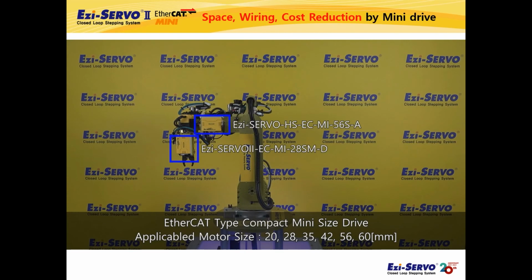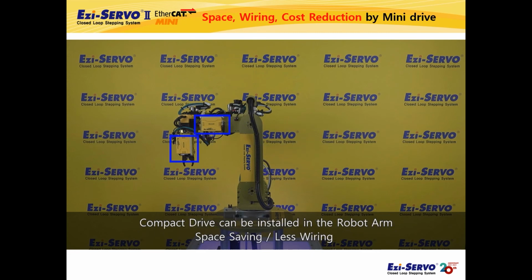First, because the mini drive is small and lightweight, it can be installed directly on the robot body. Of the 7-axis, Ezi-SERVO II EtherCAT Mini is applied to both the hollow and gripper axis. Therefore, the distance between the motor and the drive is very short, so it is possible to wire the motor cable and encoder cable very short.